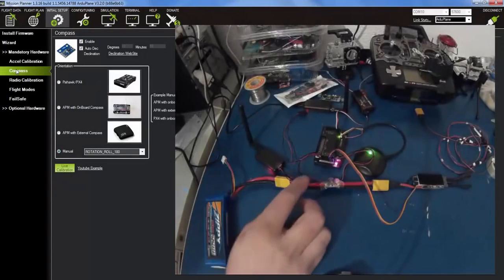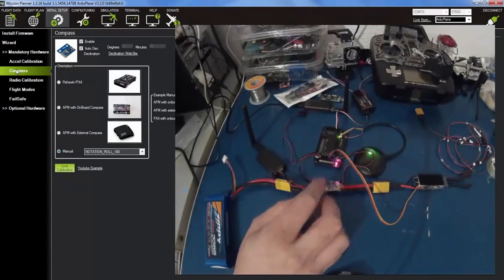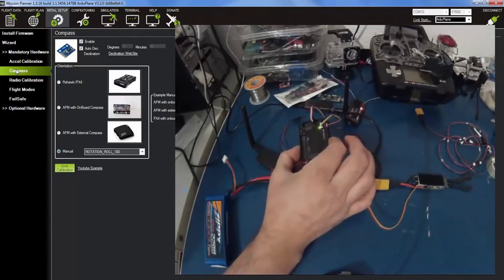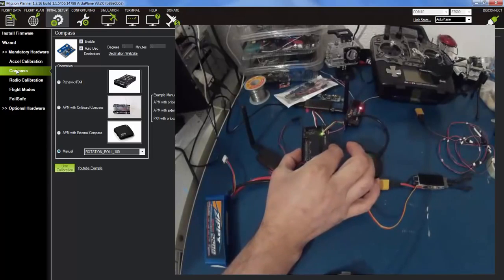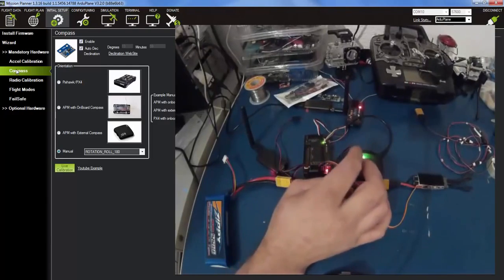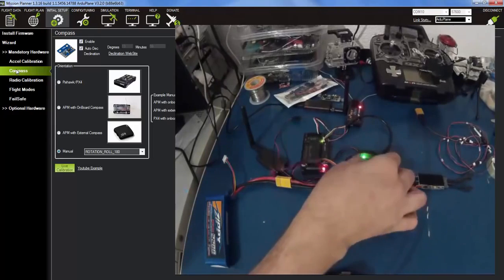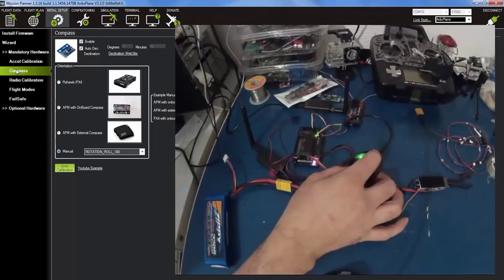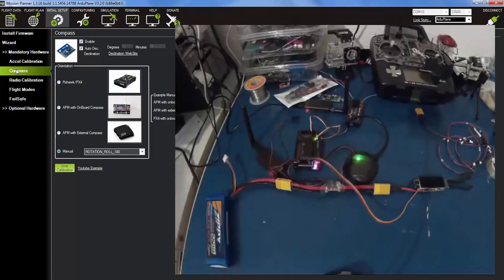I have mentioned in the first video that this flight controller has a compass inside, but if you don't like to use that compass and prefer an external one instead, like the one in the GPS module, then you have to remove a jumper there, and check the box which says enable the external compass.